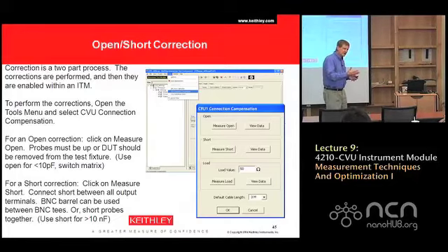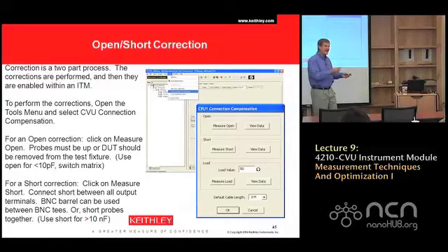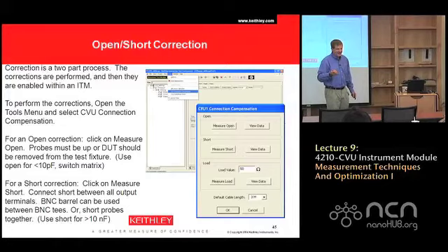So if you look at a traditional LCR meter, and the way we implemented it initially, we're basically saying, I'm assuming that you're using the proper cable and that it has a propagation velocity that I know, and therefore if you tell me the length, I know what the phase change is down the cable. What we found is that isn't true. People use whatever cable they have laying around. They hook it up and we don't know what the propagation velocity is on that.